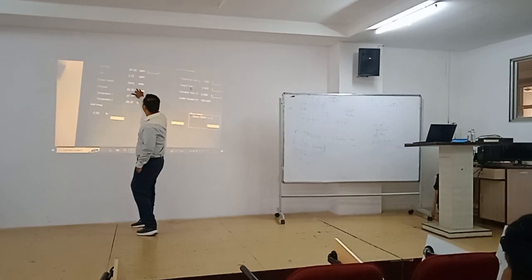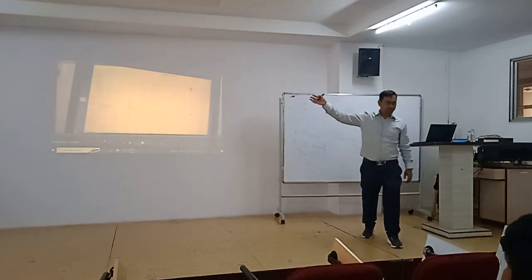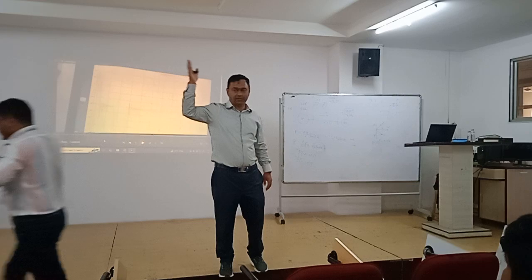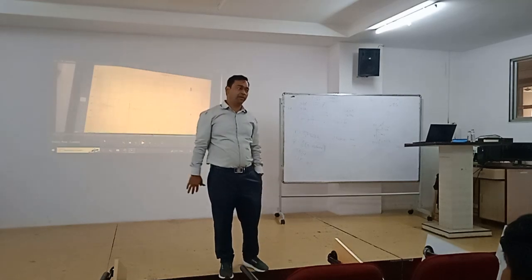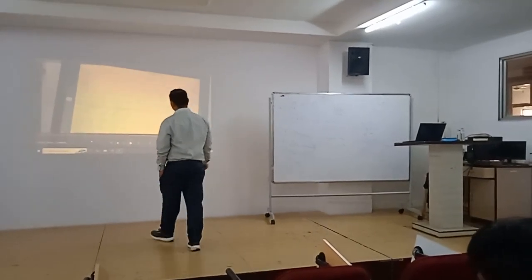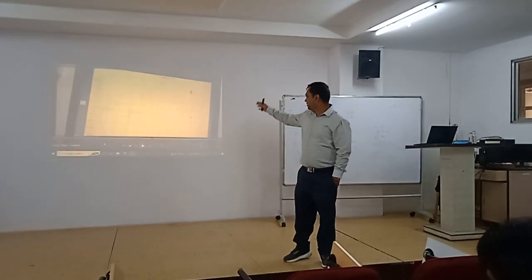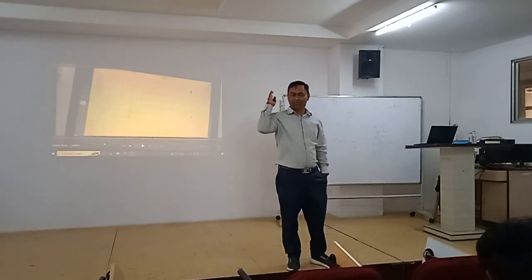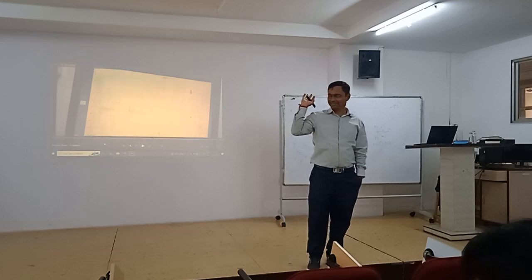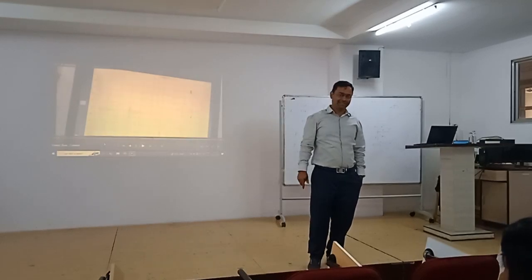See here the motor speed. It's 2915 RPM, which is actually the maximum rated speed. This is a 2-pole induction motor, so synchronous speed is around 3000 RPM, and rated speed is around 2920 RPM. That's why motor speed has increased to a very high value. But by increasing speed, will the control achieve the desired flow? No, because the disturbance is heavy.